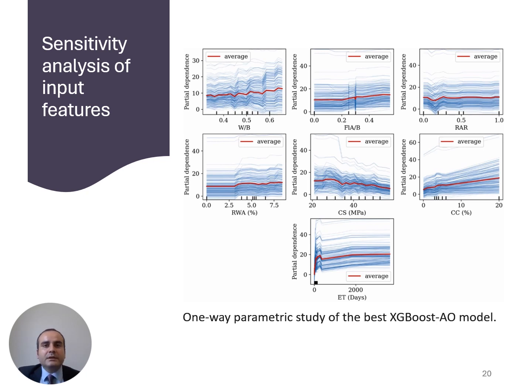The partial dependence plot visualizes the average global dependency between the developed machine learning function and one or two input features of interest, considering their marginal effects. This plot depicts the relationship complexity between the output and input features of the defined system. The one-way parametric study of the input features is depicted in this figure. There is a general increasing trend in the carbonation depths with an increase in the water-to-binder ratio and the reduction in compressive strength value.